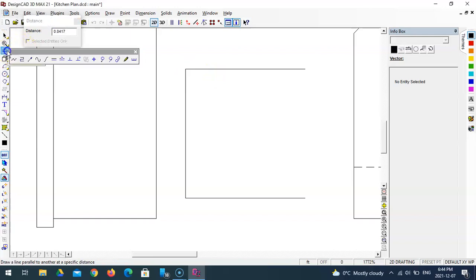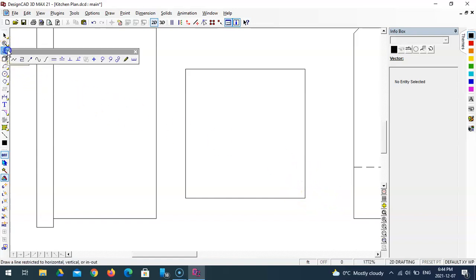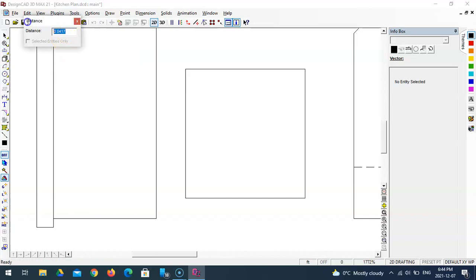So grab the ortho line drawing tool and snap to this point and this point. Then you can proceed to parallel the door inwards. So we're going to get the parallel tool, type in 1.5 inches, and parallel this by left clicking and left clicking. Now I haven't saved this yet, so before I go any farther, I want to save this. This is still the kitchen plan, so we can probably just save right over top of that. File, save. We're just adding to it at this point. I wanted to save because hatching can crash your computer, and that's what I'm going to do next.